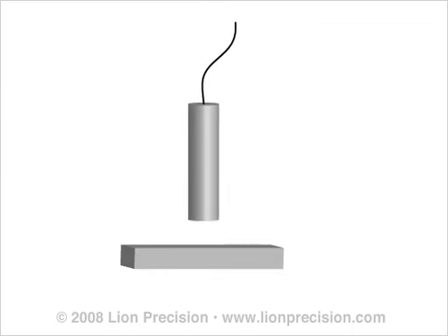Another solution to grounding issues is to use a grounded piece of flexible conductor as a brush to maintain a ground connection to an otherwise ungrounded target. Strips of copper or a metal brush will work well for this. Simply connect the strip or brush to ground and hold the piece against the target while measuring. Lion Precision Elite Series sensors provide ground connections on the front panels of the drivers to facilitate this technique.